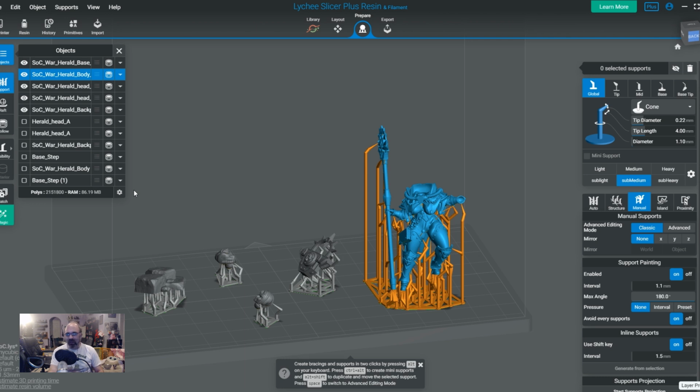There's some other things I can tell you. Don't hollow out parts that don't need them. That's definitely one I can recommend. That'll save you a lot of heartache. Especially things like heads and arms, especially when you're doing multi-part prints. Even if the character is rather large, usually an arm is pretty thin. I don't recommend hollowing them because you wind up with resin cavities, little vacuum pockets where the resin pulls in and creates an issue that will definitely come back to bite you later. So just be careful about which parts you hollow.